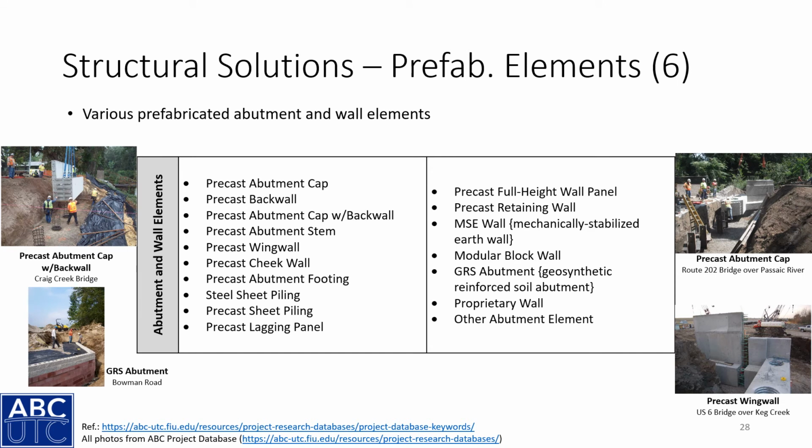Various prefabricated abutment and wall elements are shown here, and these are often used in ABC projects where you need to replace the substructure after traffic is moved.